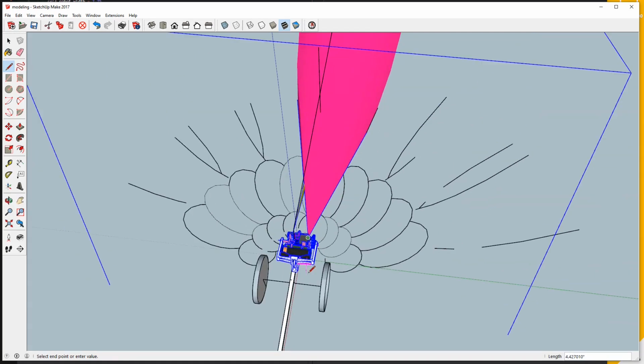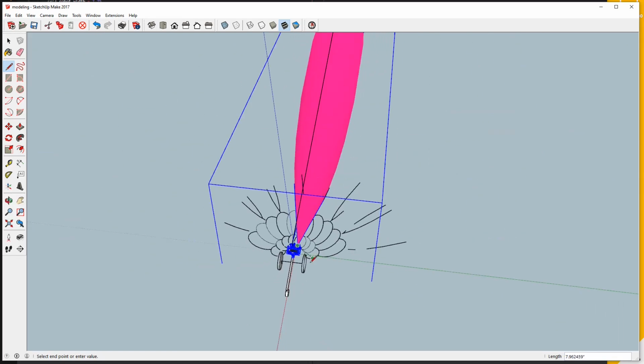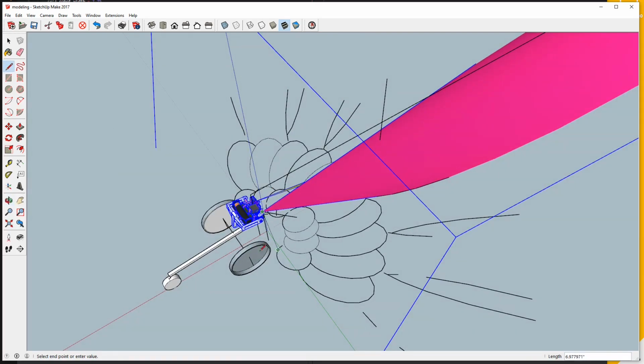And then the accelerometer on board, you figure out the displacement as it moves forward. The Raspberry Pi will tell the wheels to move forward 2 inches or 10 inches. And the IMU will corroborate that, because if you're on a slippery, non-carpet floor, it's probably gonna slip. So we'll have to keep trying to make that distance. That's more advanced.